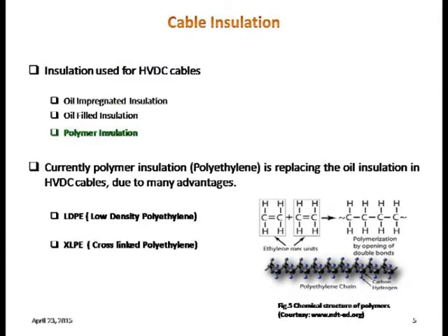Also, the temperature which the cable can withstand for this oil filled and oil impregnated insulation is just about 60 degrees centigrade. So it's also a limitation. When temperature is limited, what does it mean? The current rating of the cable will be very small.